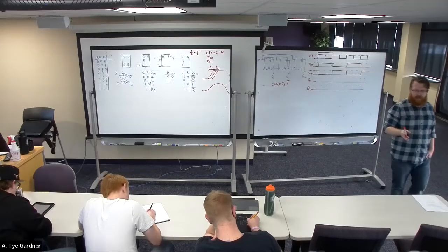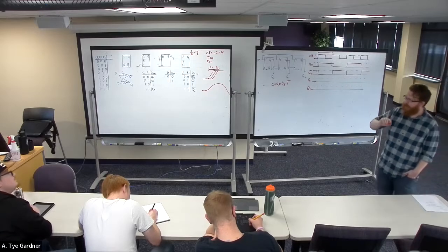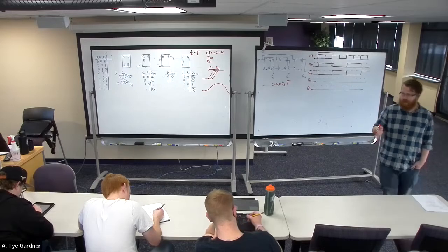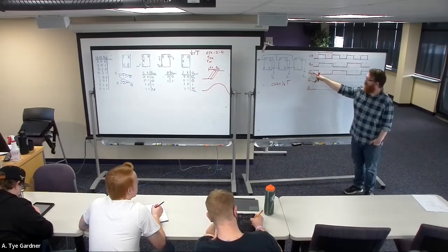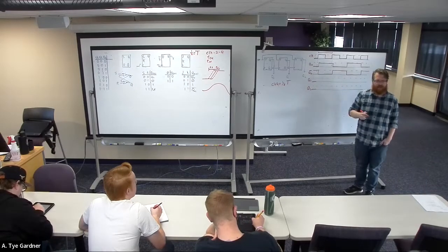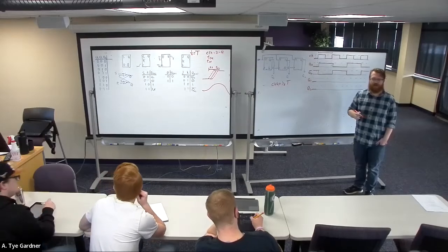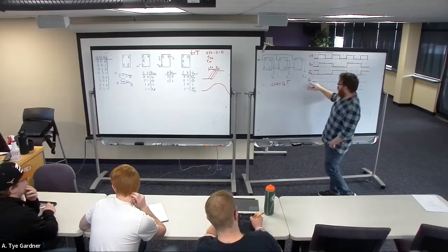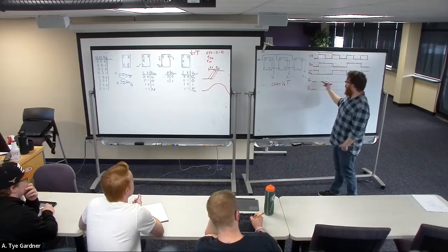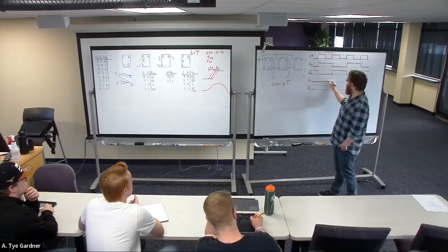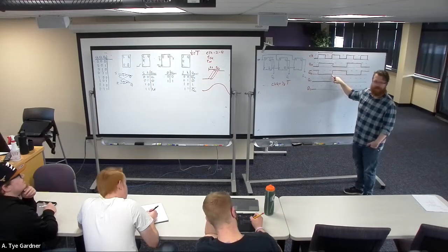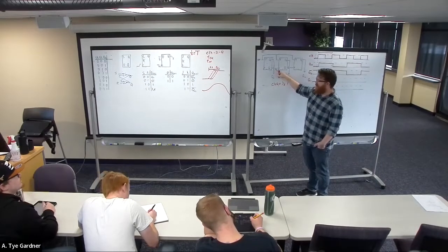Now here's what's nice. Remember how I pointed out that if that middle column has a clock that is half the speed of the first column's clock, then it would work. See this Q bar? It's half speed. We've slowed it down a whole bunch. So now this Q1 starts at 0 and in fact stays 0 all the way until this rising edge, right? Because this Q0 is here.